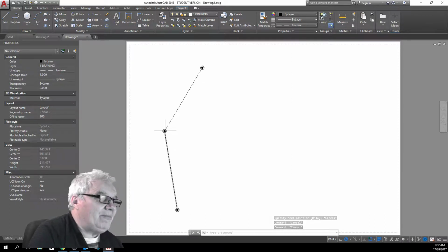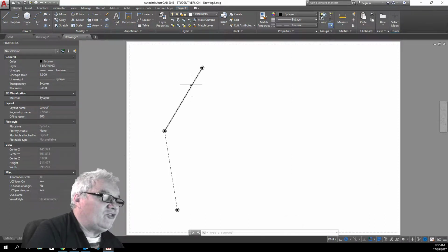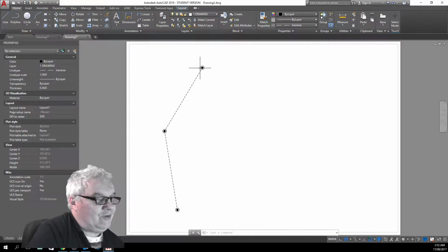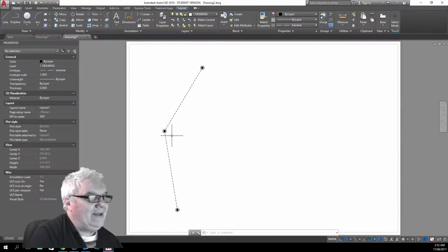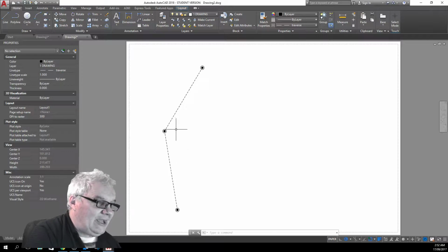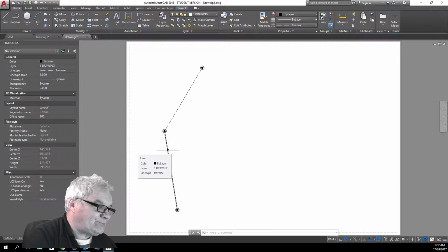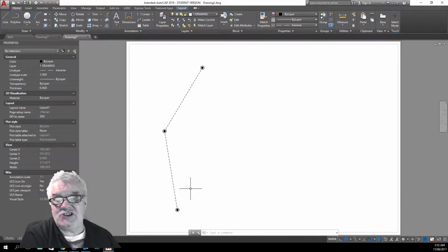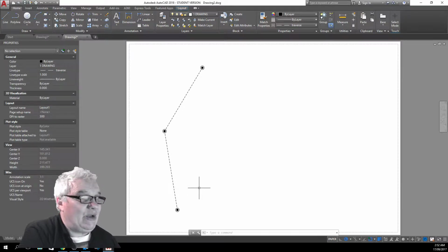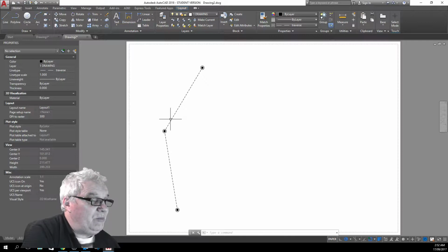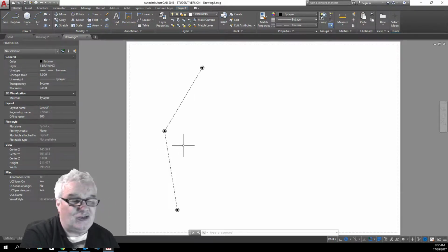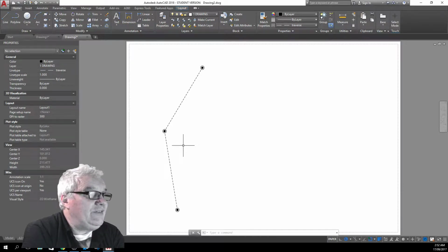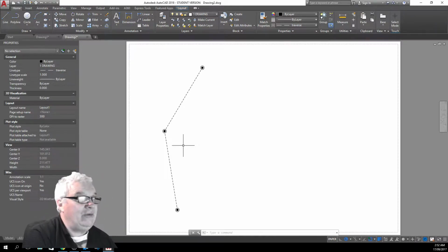We might set up on this one here, and set that bearing there. We know from our known information that we might set that bearing and turn this angle around onto this bearing, to check they agree with our old information or the information on the plans that we have, because we've got to start somewhere. Then we'll measure the distances and make sure they agree within certain tolerances, and that we're satisfied these 3 old marks haven't moved since they were surveyed and agree with the old plan, so we know where we are in the world.